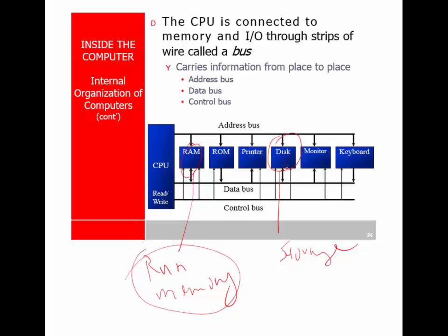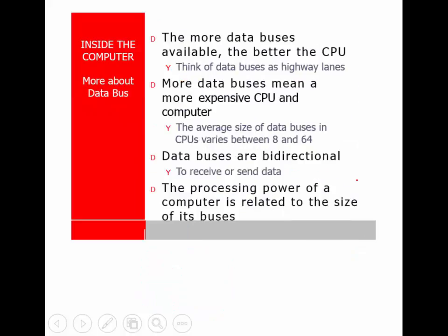The key thing we're looking at here is we've got the address bus and the data bus. We spend a lot of time talking about that, and that's how we talk between our devices. So we look at the address bus, the data bus, and the control bus. So there are 3 buses that we have to deal with. The control bus is how we control which direction data is going back and forth, who's writing it. So we're going to spend a lot of our time talking about these interfaces this semester.